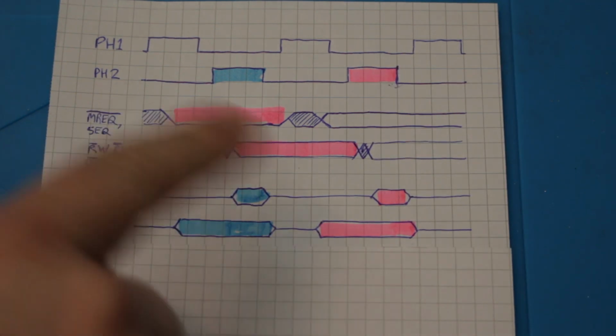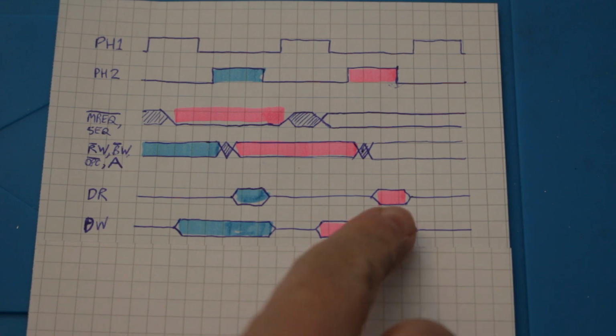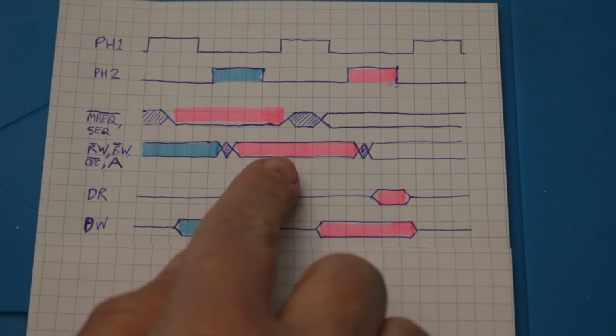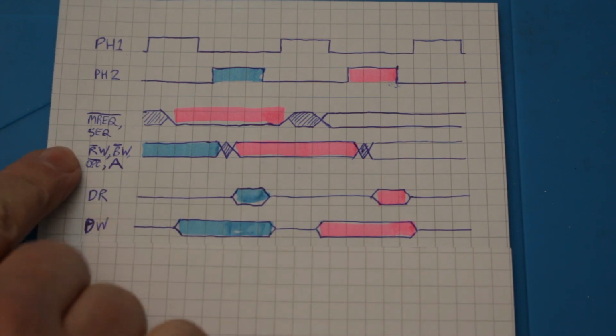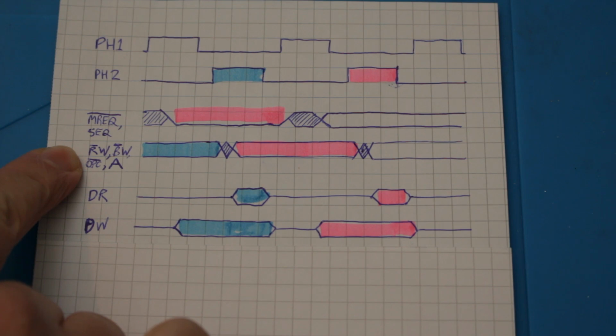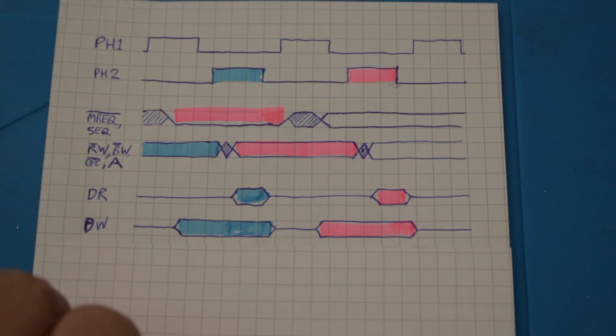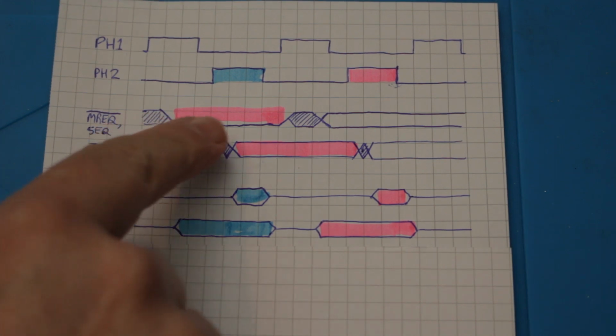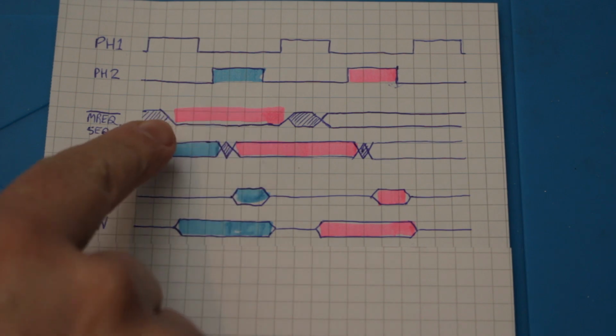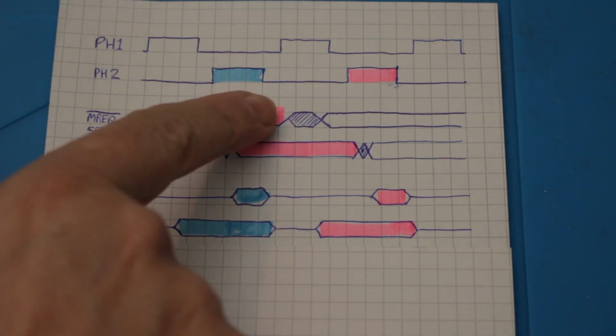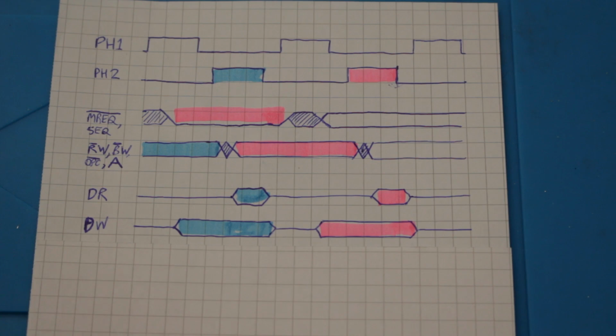So as you can see with the pipelining the way it is, at the time where we need the memory to be outputting data for the CPU to read, the address is no longer on the bus. In fact, neither is the signal that tells us that we should be reading rather than writing, nor the signal that tells us whether we should be reading a byte or a word. And finally, the signal that tells us that we should be doing anything at all is long gone from the bus. It actually ended way back here. So there's no point in time when all of these signals are valid, and we're definitely going to have to latch something.